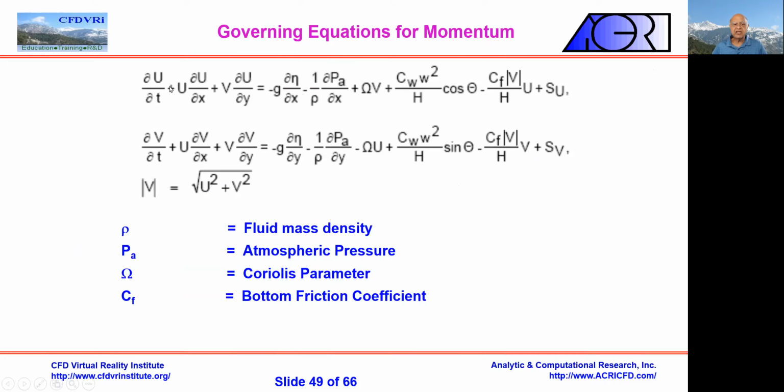Now, when you come to the governing equation, because we average them, we still have the convective flux and we have the change in time. I've taken rho out because rho is essentially typically constant. We can take it to be. If there are changes in the rho, we can deal with them in a linearized manner because the changes in water density are usually not very great. So a few percent usually.